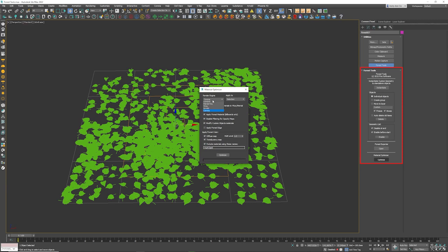And just to run through it, we've got the rendering engine. We can apply to the selection or the material library. The standard settings to apply. One thing to know is the exclude materials using these names, so trees and barks. These are the names of the materials that Forest Pack have given us, where it will ignore the forest color node. So if you remember, the forest color node was needed in order to create certain effects in the material rollout. The exclusion will be anything that has the name tree and bark in it, because those ones don't actually need to be changed in terms of tinting.